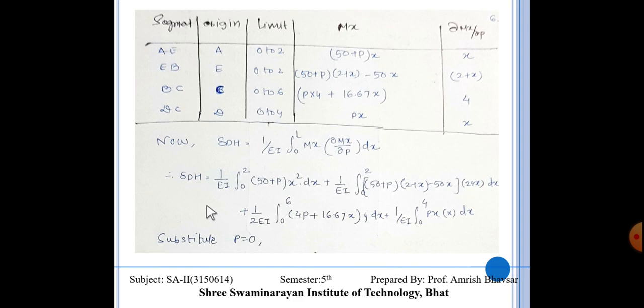So delta DH is equal to 1 upon EI integration 0 to 2, (50 plus P) x square dx, plus 1 upon EI integration 0 to 2, ((50 plus P)(x plus 2) minus 50x) into (x plus 2) dx, plus 1 upon 2EI integration 0 to 6 of (4P plus 16.67x) into 4 dx, plus 1 upon EI integration 0 to 4 of Px into x dx.